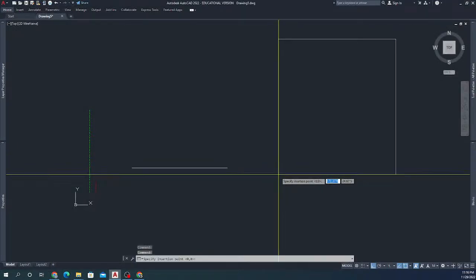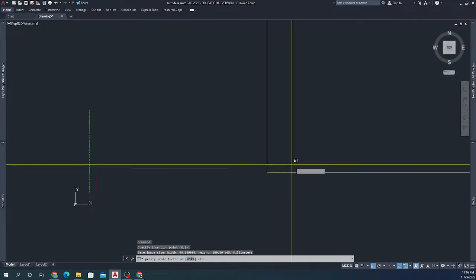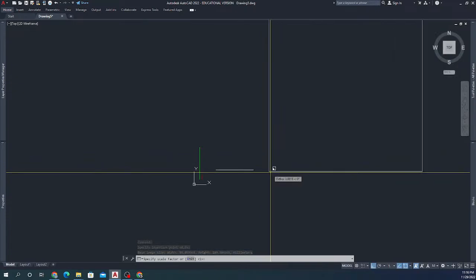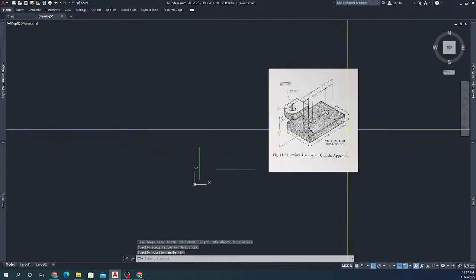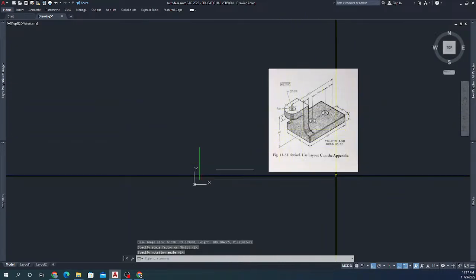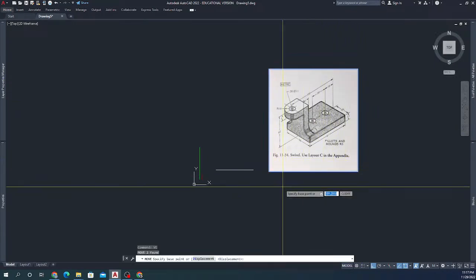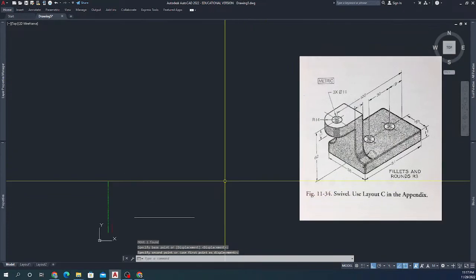just drag it right onto your AutoCAD icon and let it go in space here. And then I can see how big my first view is going to be. So I'm just going to set this next to it. And then I can zoom out and scale the window if I want. I want it kind of relatively small, so something like that will probably work. I'll just click and then hit enter for the rotation, and it'll pop that into your AutoCAD screen. You can move this around if you need to. So I'm going to move it over a little bit while I'm drawing, but I'll leave it here so I can reference right on screen.